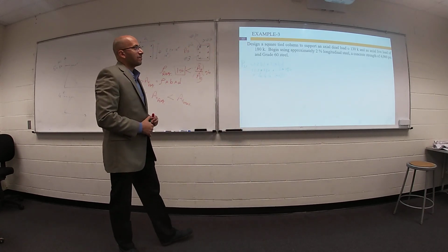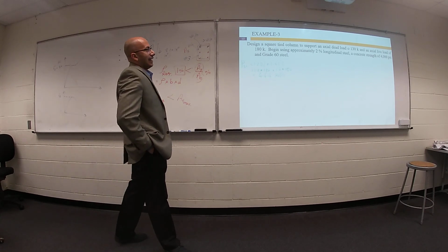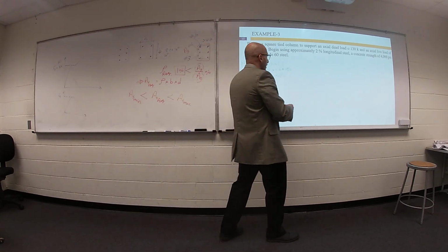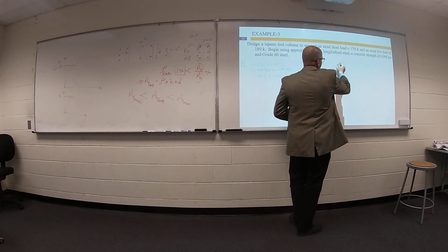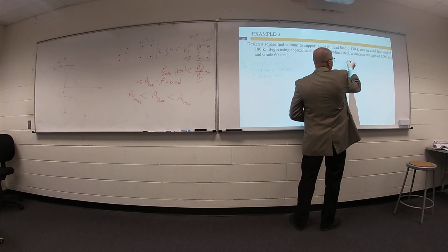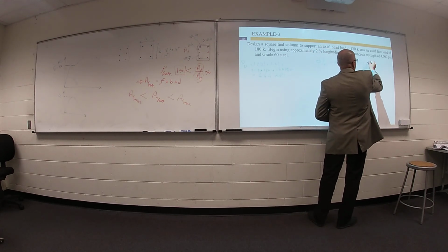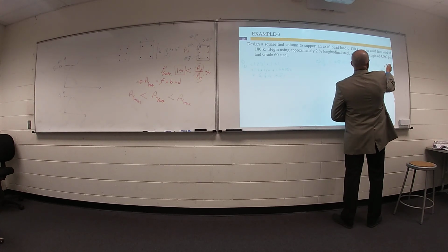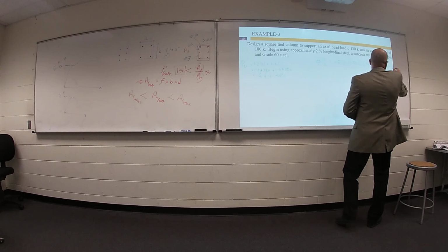Your value is 444 kips. Okay, that's fine. Phi Pn equals 0.8 phi times 0.85 f'c times (area gross minus area steel) plus F yield times area steel. Do you agree?